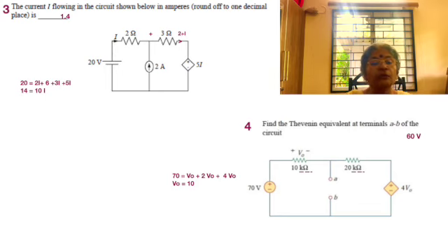So let's start. What do we know? We know that I comes in. The 2 amps from the 2 ampere source joins it, and together they flow into the dependent source as 2 plus I. Now we have the overall current distribution, and then we take Kirchhoff's voltage law.